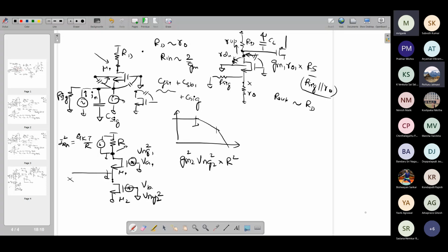Okay, so the first part of the answer was probably correct. The second part is probably not so correct. But anyway, you are correct that you are getting a source regeneration over here. So for M2, if I look at the input noise or the gate noise signal for M2, just like in the case of cascode, this one is going to have a source regeneration, and that source regeneration resistance is nothing else but RO2, which is large, and therefore the gain from this VNG to output is going to be small, and therefore we can ignore it effectively.